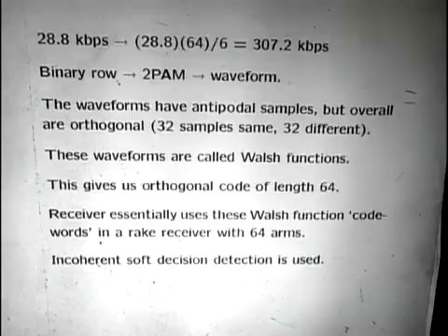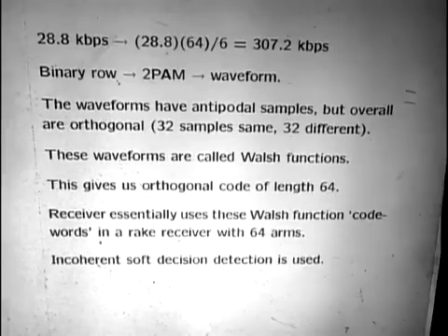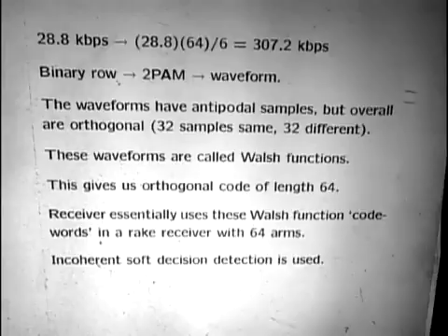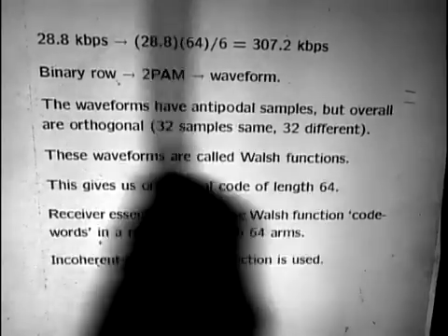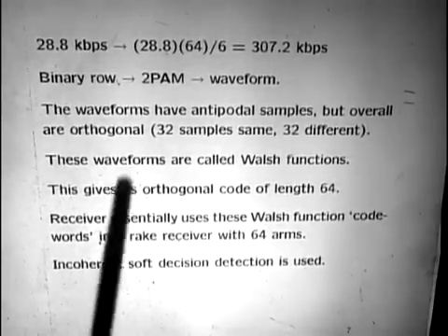What we're trying to do is get ourselves, by hook or by crook, up from these very small bit rates that we need to represent voice up to these large bit rates, 1.25 megabits per second, which we're going to spread this waveform to. All the reasons we want to spread the waveform, I'll talk about them later, but for now let's just think about it as saying somehow or other we want to spread the waveform out and turn a small number of bits into a large number of bits. So we've done a pretty significant part of that right here.